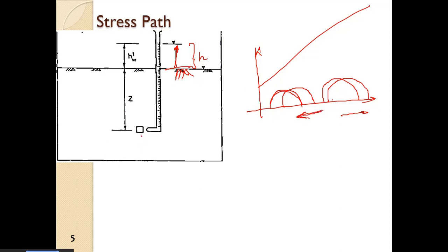So in case of an earthquake also, there is a rise in pore water pressure. We can represent it as a rise in groundwater table as well, but it is better not to represent it that way because it gives a wrong kind of impression, because that is due to the vibration in the soil element.